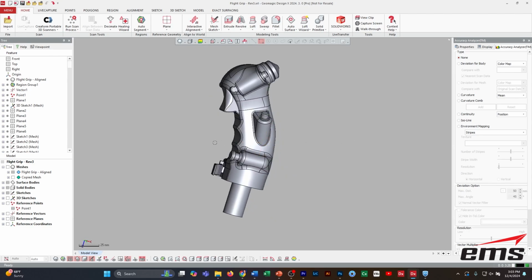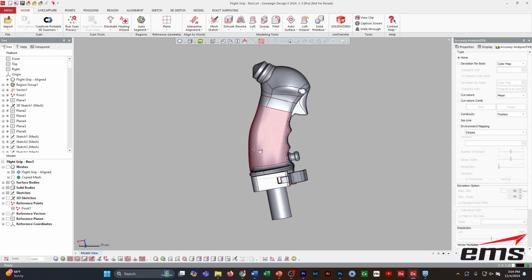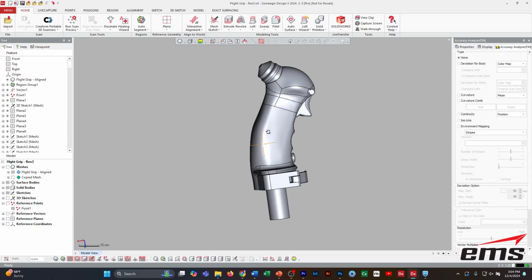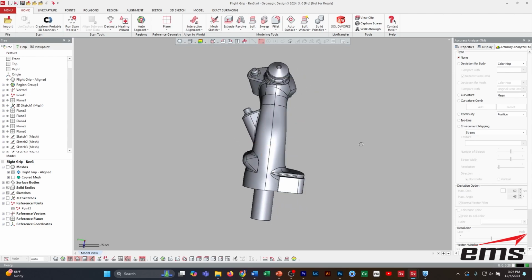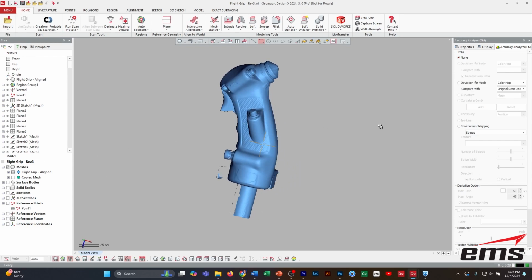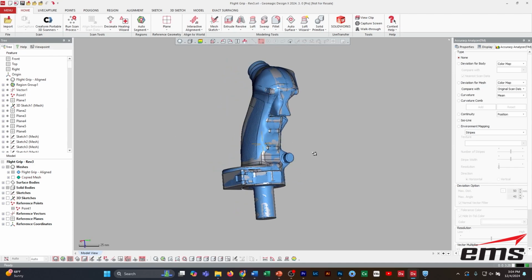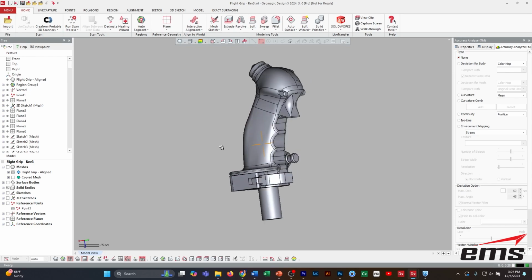So now the advantage of this surface type or model type is it's much easier to edit downstream in your CAD system. Now, it's the same scan data as before, but when we built this, you can see it looks different because it really is. Now, so the advantage is it's a better model. It's more intelligent. You can edit it.